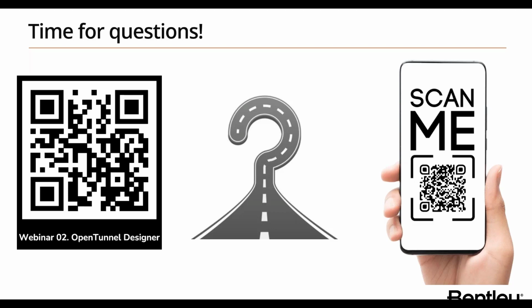Giacomo already left, but he had a second question and a third one. How do you model the intersection with crossing elements, such as cross passages or technical rooms? The cross passages can be modeled as transversal tunnels. So basically, it's another tunnel. And we have the MicroStation tools to do Boolean operations. So basically, the user can say, I would like to cut this lining part with this shape coming from the other tunnel. And in this way, he has full control on intersecting the solids and creating the geometry that he needs there.